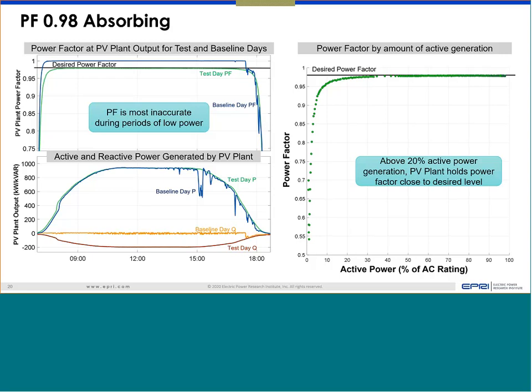But on the other hand, when it is 0.98, you can clearly see that it is almost linear to the active power. Power goes up, reactive power goes up; power becomes flat, saturated, reactive power also becomes flat, and then comes back when the power goes down. So in power factor mode, reactive power is proportional to the active power. Whether it's 0.98 or 0.95 depends on the ratio, but it's almost linearly related. It doesn't matter what the voltage is: when the real power goes up, reactive power will go up and follow that trend.